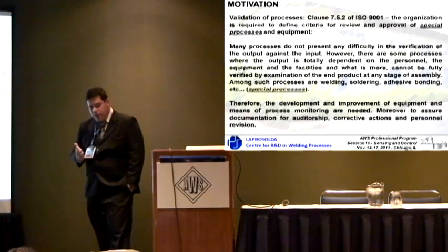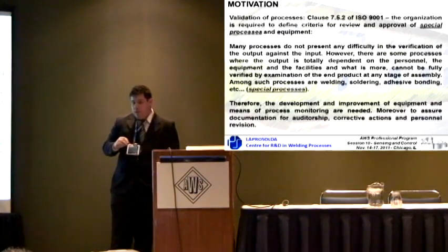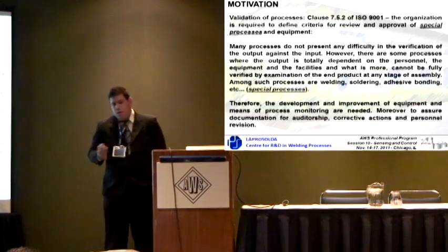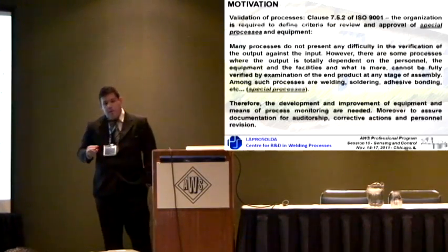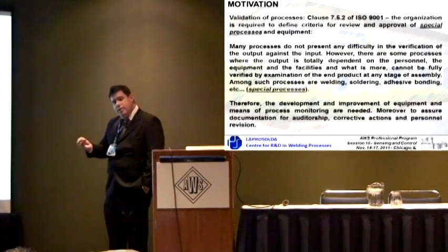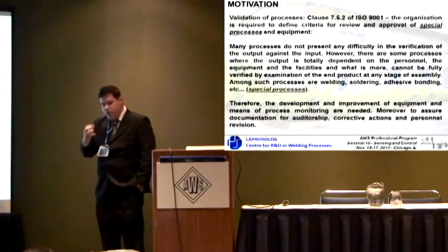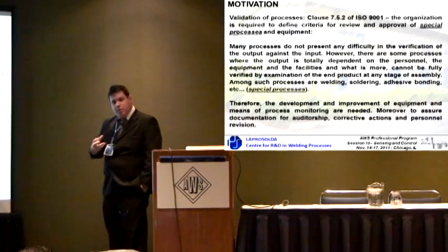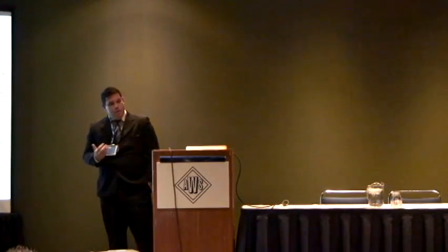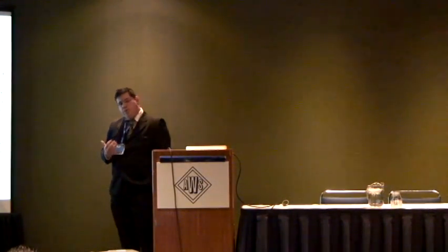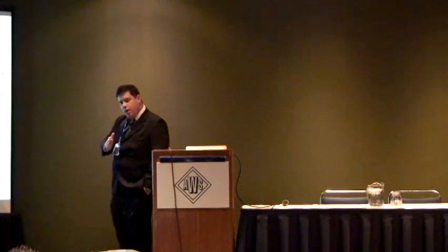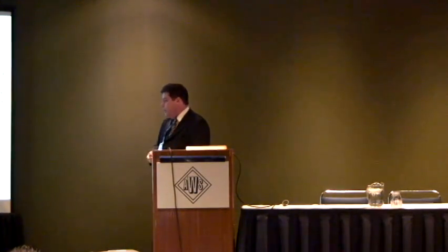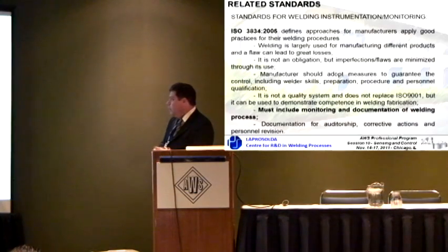In welding, for instance, we cannot only do a final inspection. If you weld stainless steel and choose the wrong consumable, wrong wire, or wrong shielding gas, we may still get a good final bead, and the inspector says there's no porosity, no lack of fusion, a sound bead, even though the whole process was carried out wrongly. So in a special process like welding, we have to measure the whole chain of production, and in that chain we have, in our case, the electrical signal.